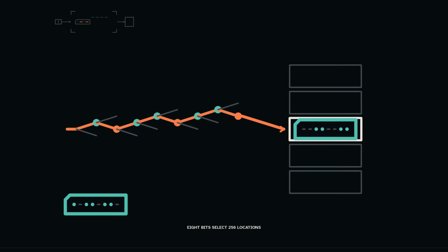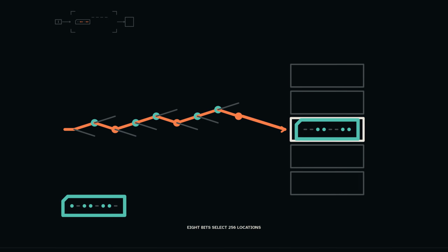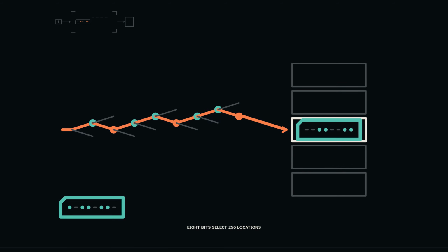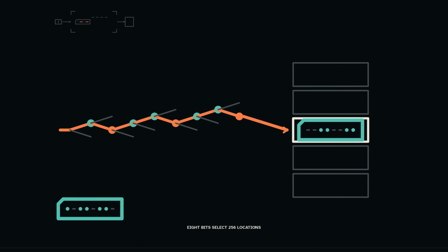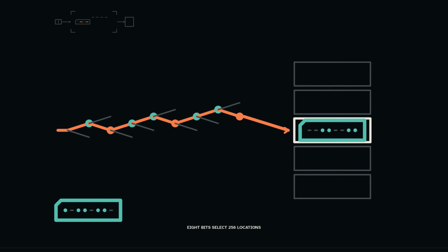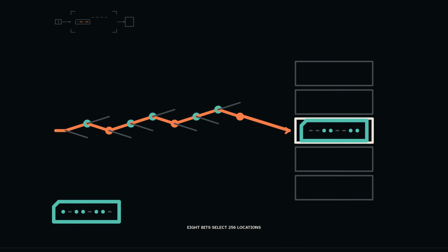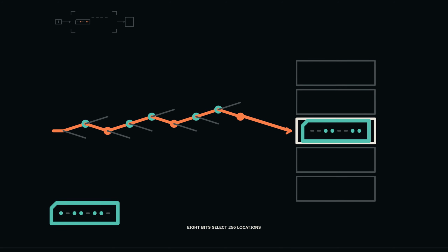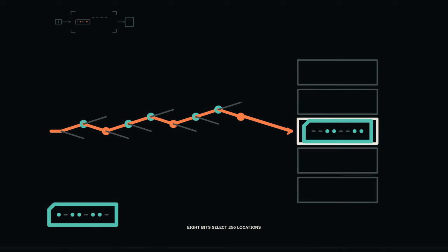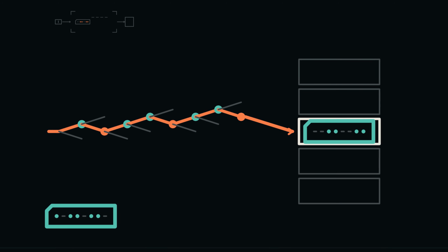Predict which module belongs beside a bank of registers during a write. The decoder, because one destination needs an enable. During a read, decoder selection can identify the row, while an output selection network forwards that row's byte. Selection is not one universal box. The direction of the relation matters.